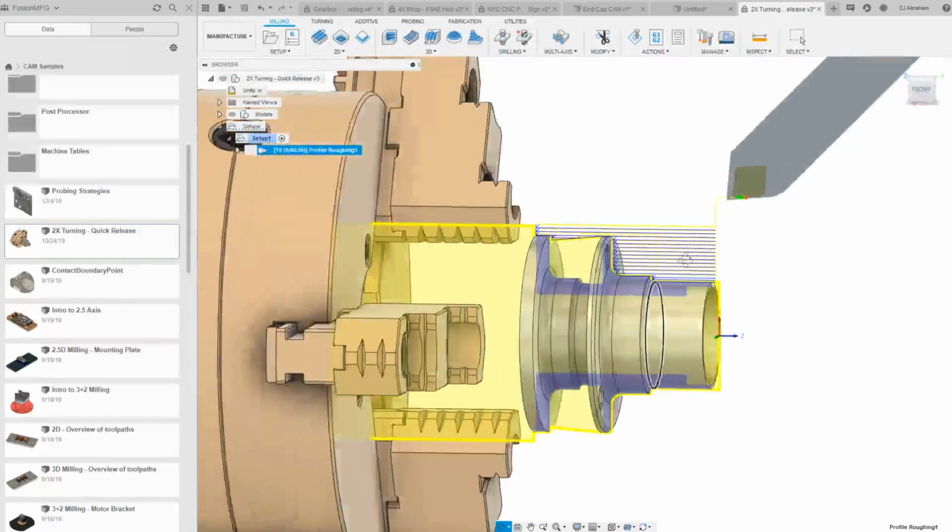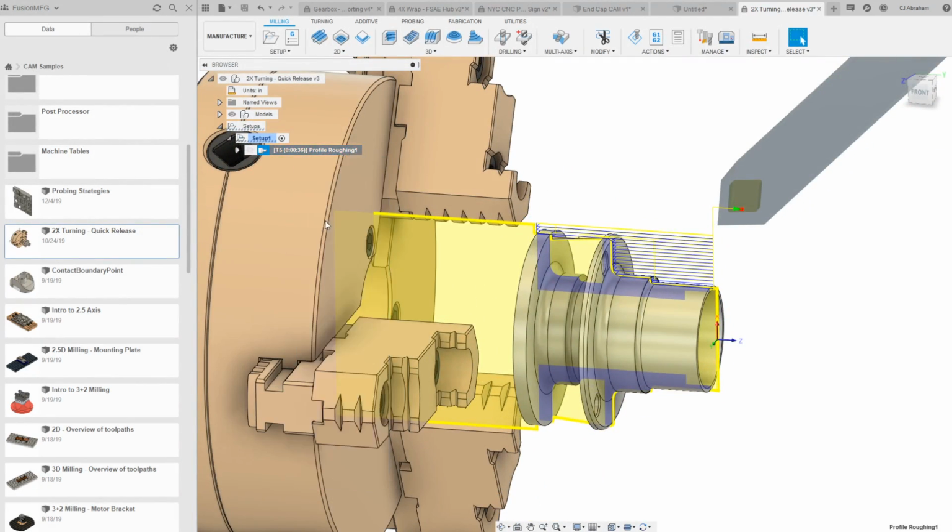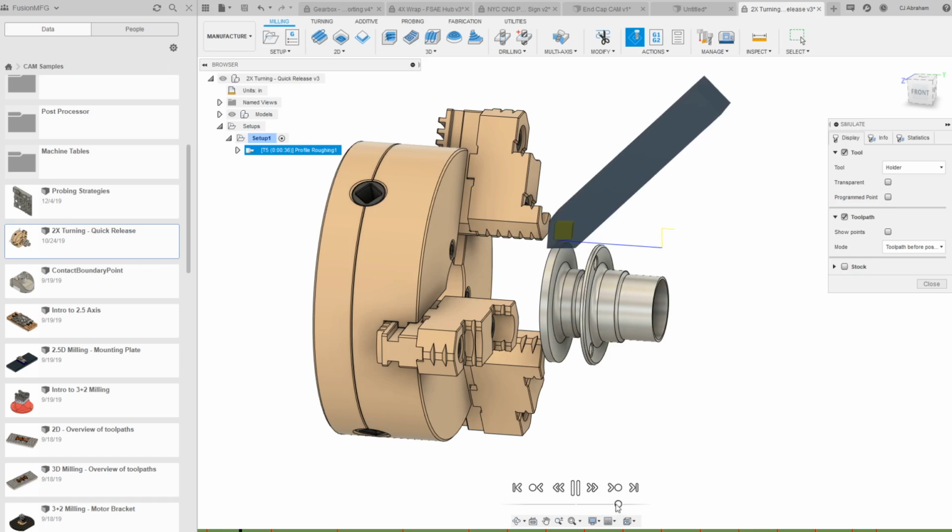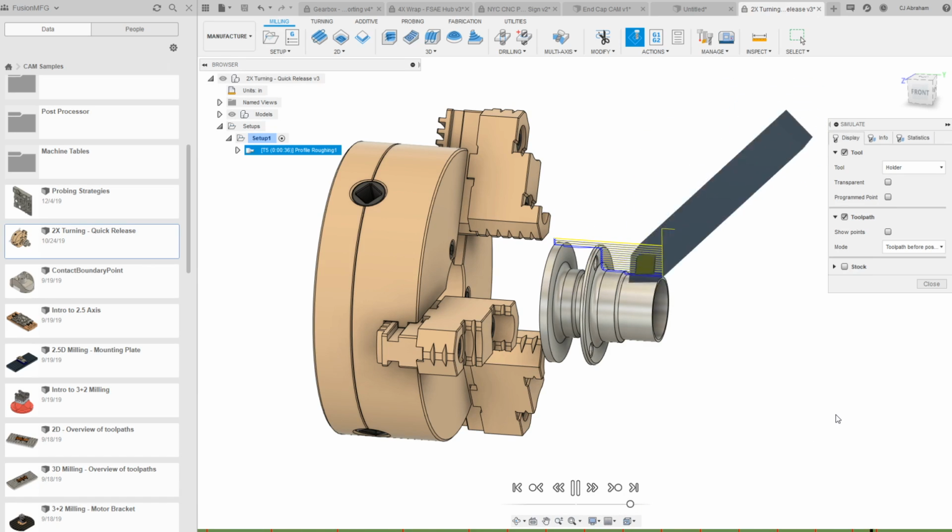Okay, so there's your turning roughing toolpath with the tool tilted at 45 degrees. Again, you would have to make sure that it's set up in the way that you need it for your machine and the post is able to handle that and things like that. But otherwise, from a UI standpoint, this is all it takes. Okay, Al, were there any other questions about...